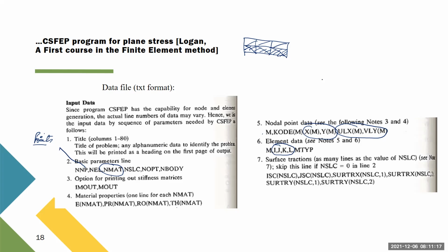In general, this program was set up to work with this type of element. But in our case, we are working with triangles. Since you need 4 joints, for this triangle you need I, J, K, and you repeat the number of the last joint. The program understands that if K and L are the same, you are using triangular elements.